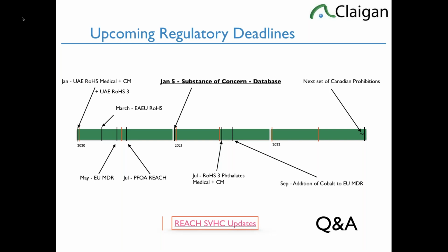And the big doozy one for medical is cobalt. Unless they change the rules, it will enter into scope of regulation for EU medical device regulation, EU MDR, in September, which basically brings stainless steel into regulation for EU MDR. That is going to cause complexity unless somebody sorts that out, because most stainless steel has cobalt between 0.1 and 0.2%. It's normal.